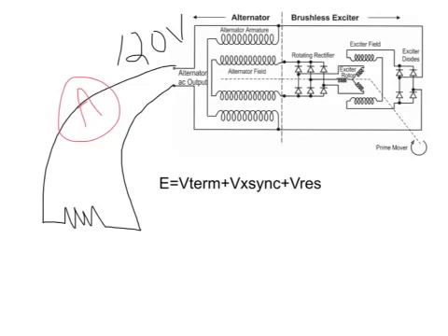We already know that the voltage across the load is going to be 120. Neglecting any resistance in the lines, we're really measuring at the same point as our alternator output. So now we've connected load and current is going to flow. Now that current is flowing, we are going to have some internal volt drops. One of them is the voltage dropped across the resistance of all of the armature conductors. The other one is voltage X sync.